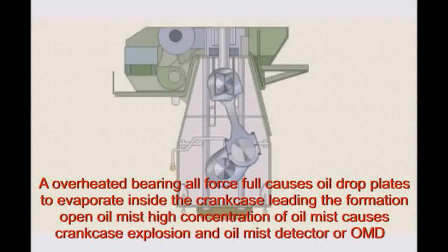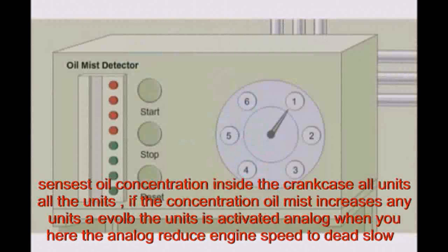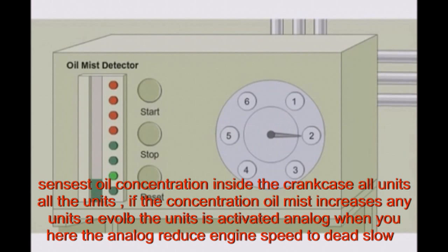An overheated bearing or hot spot causes oil droplets to evaporate inside the crankcase, leading to the formation of an oil mist. Higher concentration of oil mist causes crankcase explosion. An oil mist detector, or OMD, senses oil mist concentration inside the crankcase of all the units. If the concentration of mist increases in any unit above the limit, it activates an alarm.